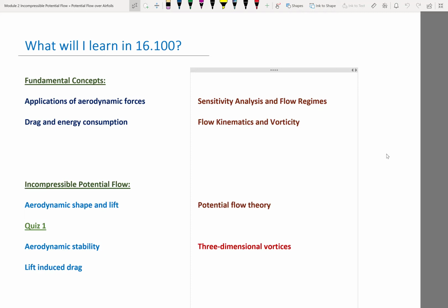Remember, there are 3 fundamental building blocks of an incompressible potential flow. What are the 3 elements? The first element is very simple. Vortex? Actually, that's the second component. It's not even the simplest component. Free stream, right. The first one is free stream. It's just a uniform velocity. It doesn't have to be just along the x direction. It can have a component in the y direction too, right? So uniform velocity is the first component.